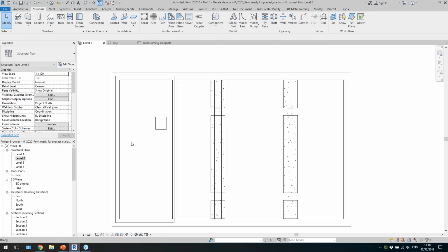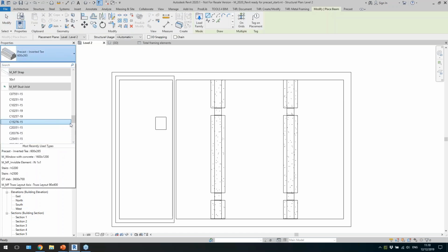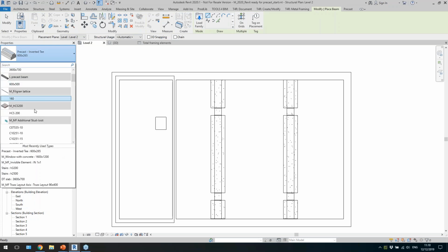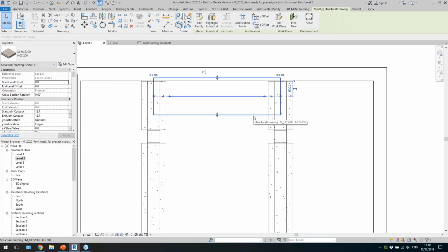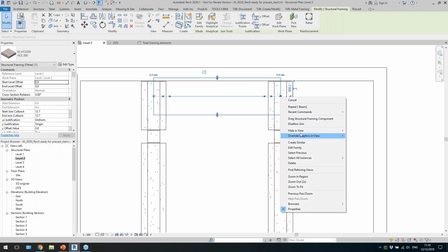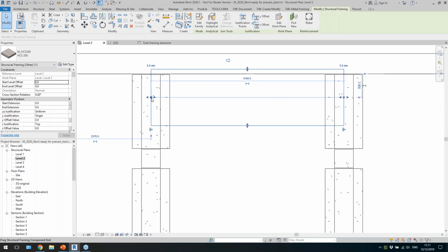And again, if I want to create slabs, maybe I can just draw a different shape of a beam, right? So let me go here, pick the type of beam I want to create, just draw it from here to here, and then usually what I do with this type of beams, I just disallow joints because I really want to manually control the position of them.